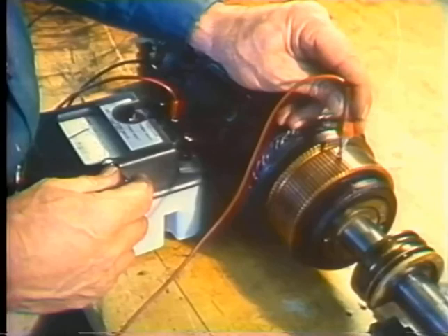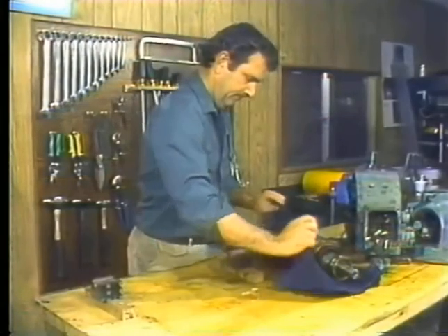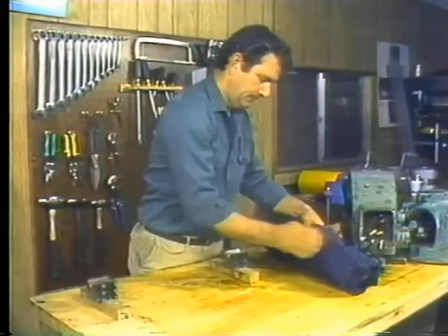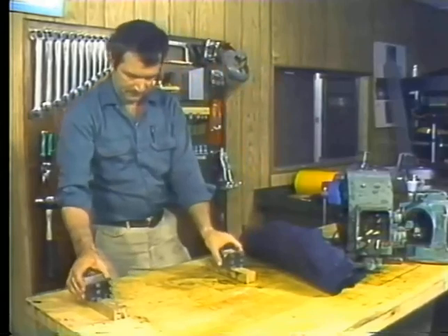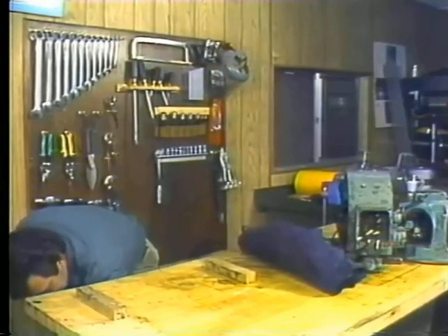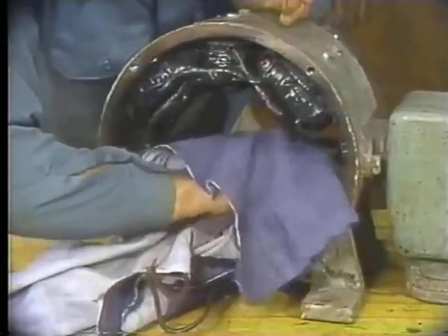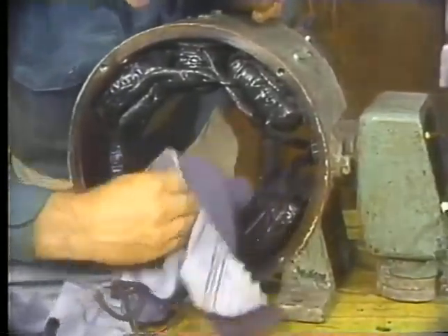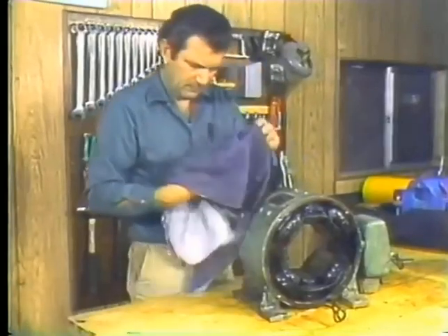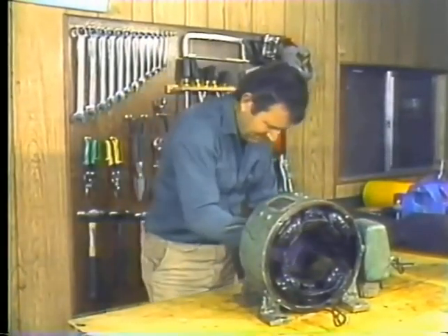After that, you can be sure the armature's good and it's ready for the bearing. Now, we're going to use a press to reinstall these bearings. Then we're going to cover the assembly and set it aside so it won't be damaged while we continue the rest of the inspection. Next items on the list are the motor frame and the field poles. They've got to be cleaned real good first. Pay special attention to the area between the main poles and around the interpoles. Clean out all the dirt and carbon dust.